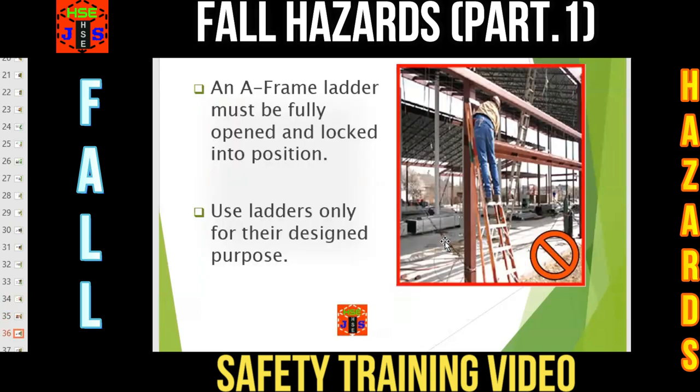An A-frame ladder must be fully opened and locked into position. Use ladders only for their designed purpose. By the way, the person who is using this ladder is not using it for its designed purpose, and this type of work practice is unsafe, not acceptable, and it may lead to a potential workplace accident.